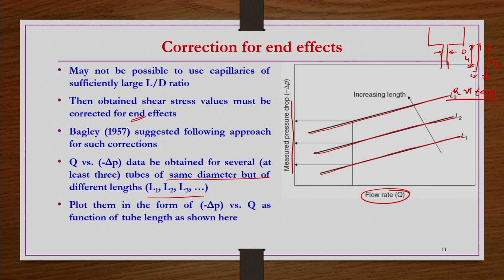Okay. So, with increasing length, for a constant flow rate, the pressure drop also increases. That is what you can understand with increasing the length. Now, from this volumetric flow rate information you get velocity, and from this velocity you get 8 V by d. So, for each flow rate, what is the corresponding 8 V by d, and then you draw a line here and measure the pressures. That information you may require for further calculations.